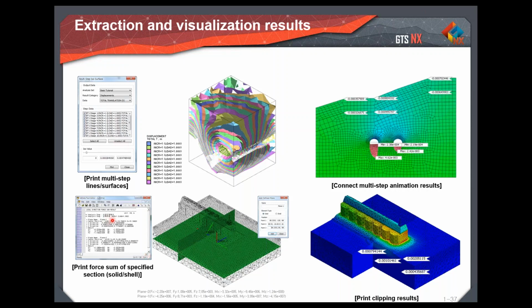And as I was talking about this particular text value, this is your LDF sum, that is local direction force sum. Basically, in the solid elements, we never find the bending moment diagrams. We cannot find axial force in all cases, because we can only find stresses. We can find displacement in here. So in order to find, let's say, the bending moment diagram even in the solid elements, we need to go for local direction force. We will develop a surface where I'm interested in finding the bending moment, and then I will ask the software to calculate the bending moment in that plane, and it will provide you with the text format.